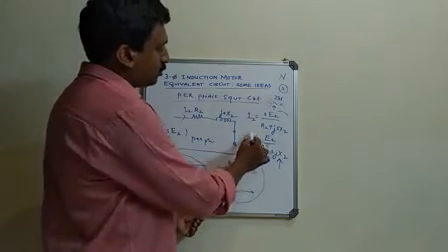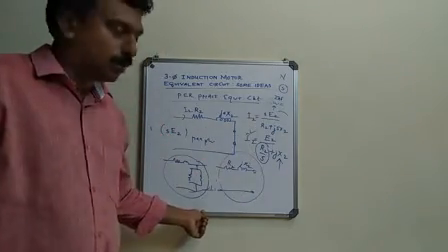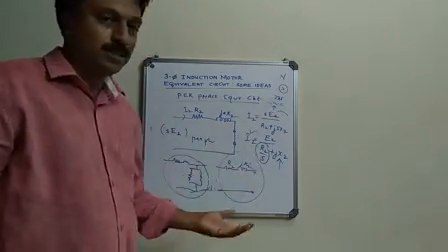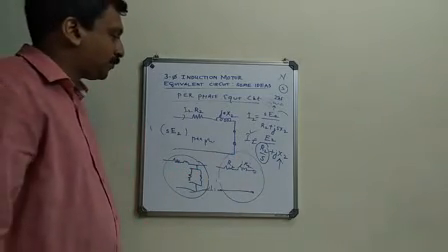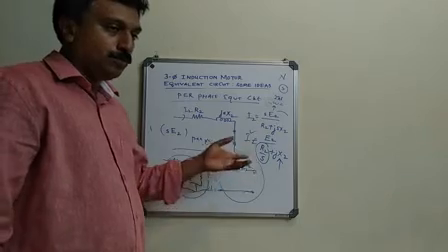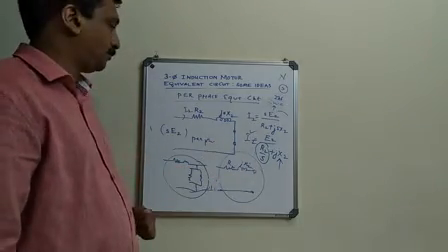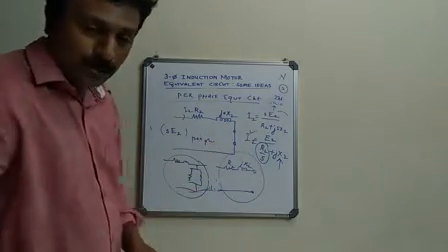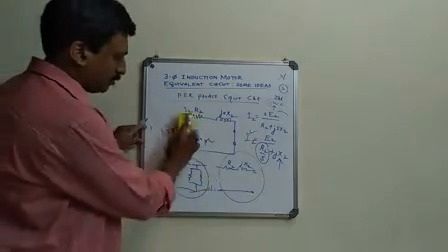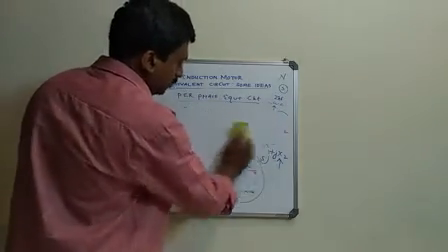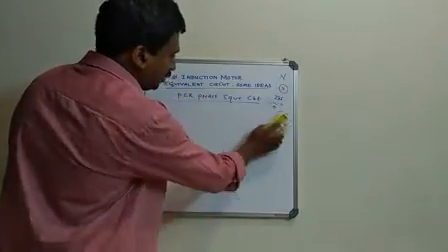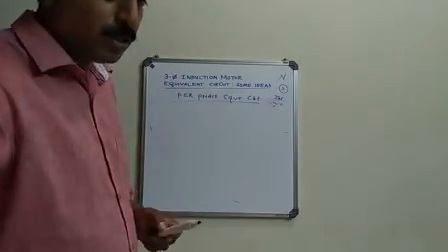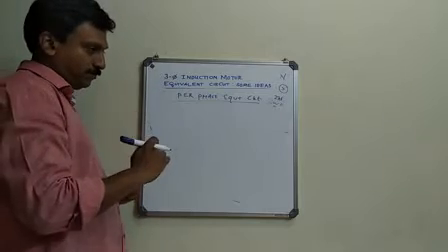So this I2 is the same, and your resistance is manipulated to a value that gives a convenient way of representation. So you can change this rotor circuit to a new form, to make it ready to be connected to the stator.